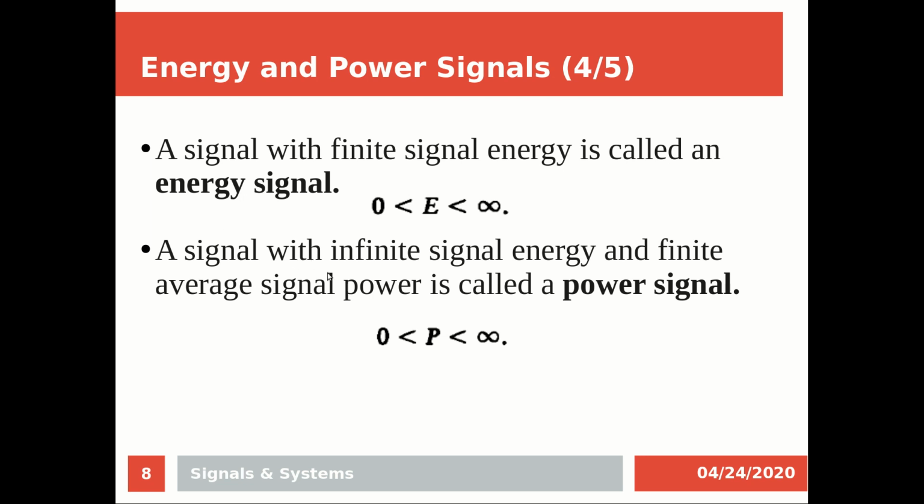If the signal has an infinite signal energy, but it has a finite average signal energy, that is, a finite signal power, then we call it a power signal.